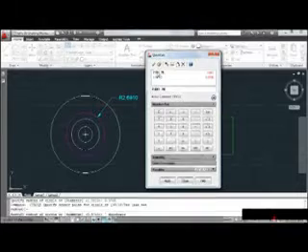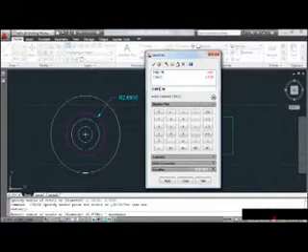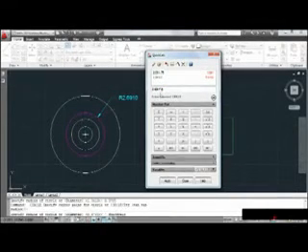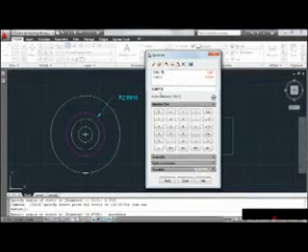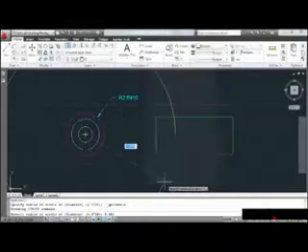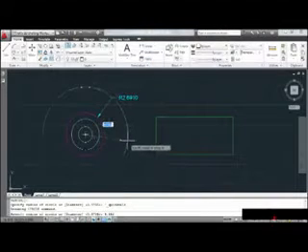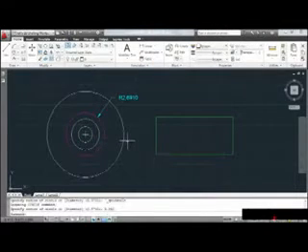I'm going to double-click on this first equation, and then I'll click, hold, and drag across this text, and change this to multiplied by 2. Notice I'm using the asterisk symbol. Asterisk represents multiplication. And here's another shortcut. We don't have to push the equals button. If you want, you can simply come down and click Apply. And then I'll press Enter to finish.